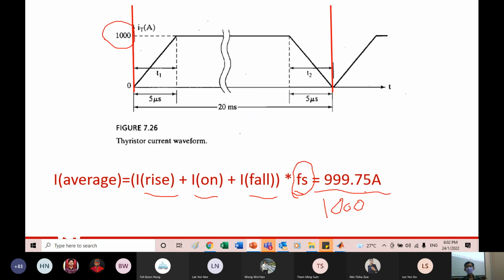So you can see for a thyristor, they switch at a very low frequency. Remember the switching frequency: the higher you switch, the more loss you get. It's multiplied by a function of frequency. Of course, the advantage is that at high frequency, a lot of your inductors and all these components can be very, very small.